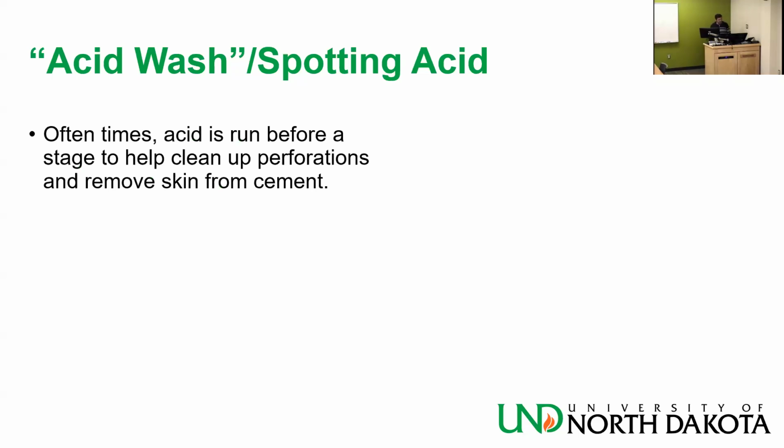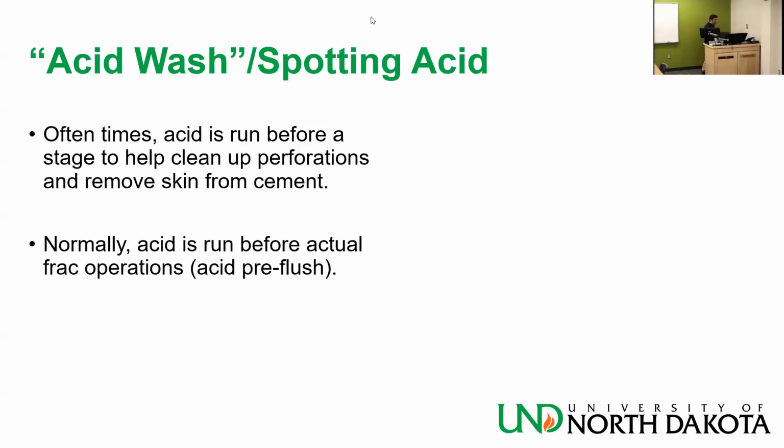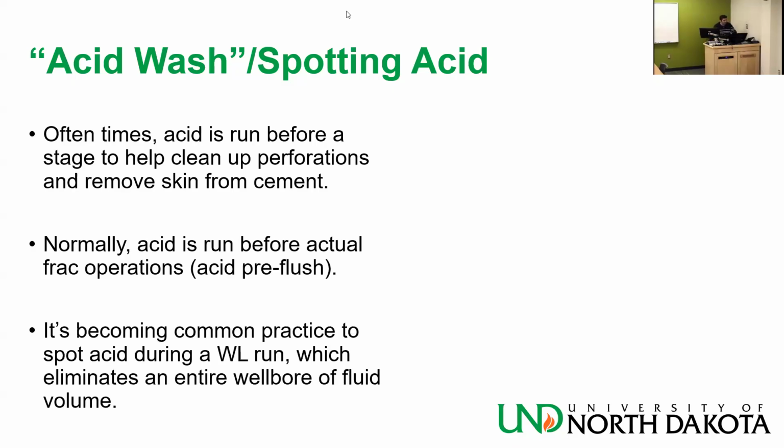Oftentimes, acid is run before a frac stage to help clean up perforations and remove skin from cement. Nothing new. Normally, acid is run before the actual frac operations. We call that acid pre-flush. It's not exactly the same as acid wash, but it has similar objectives.